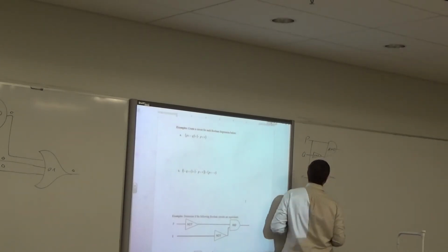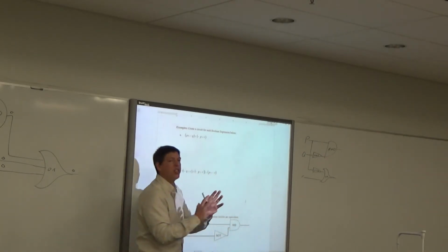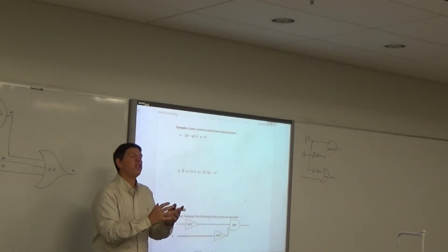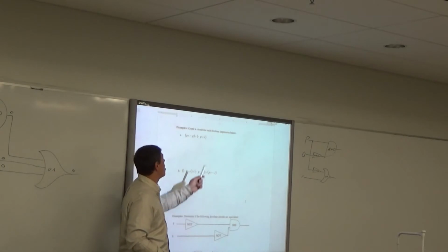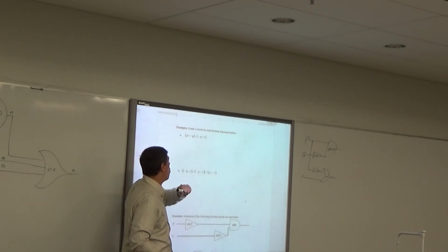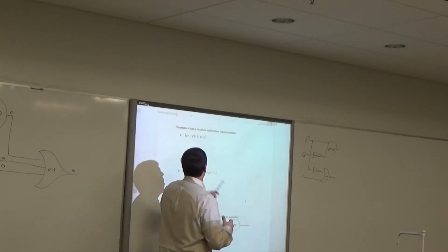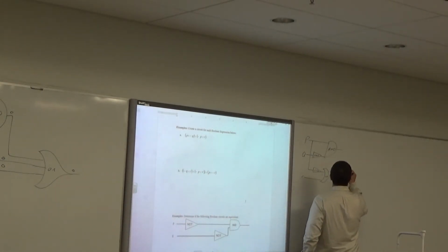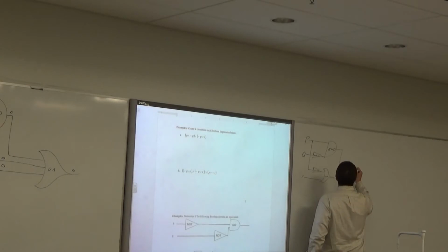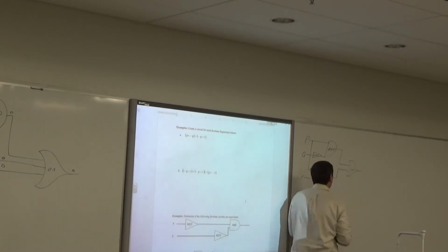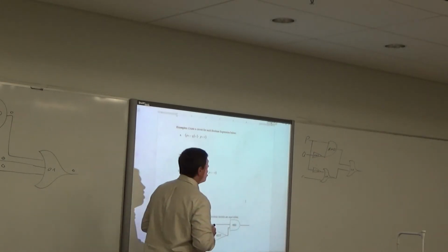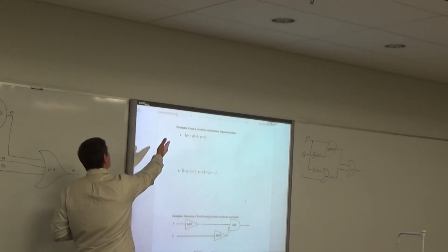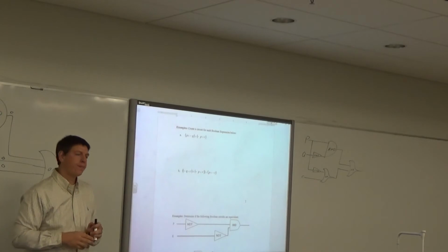So now what happens is, I have both of my parentheses done. Inside the parentheses, I follow the order of operations. The last thing I notice is that I have an OR that's going to connect those. So I've gone in the parentheses, now I can connect the OR. So this might be one possible circuit. Not saying it's the only one. But this is one possible circuit that would represent that Boolean expression.